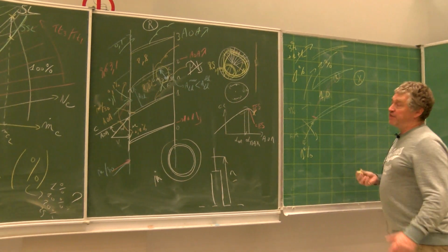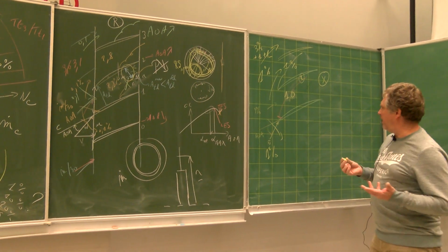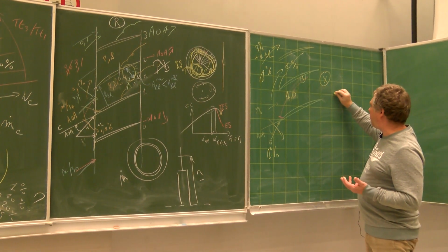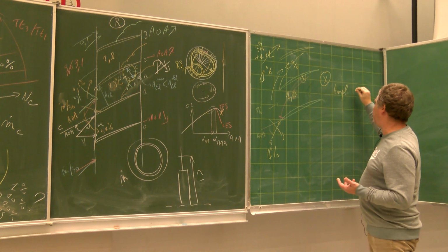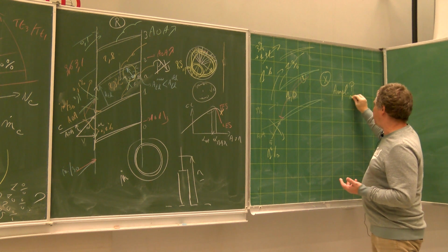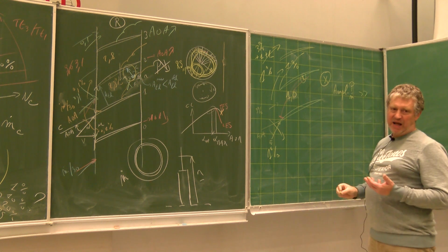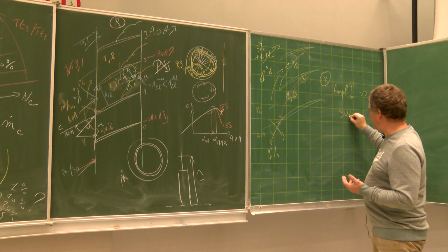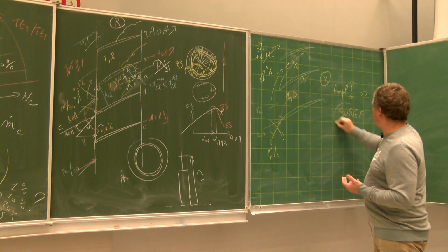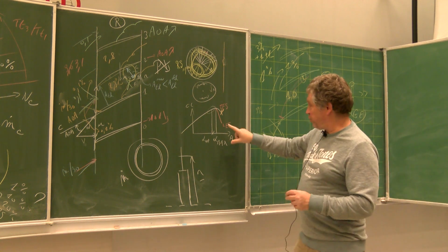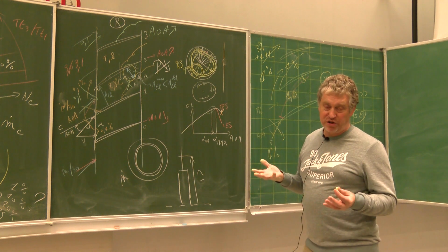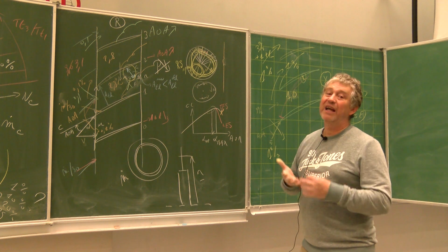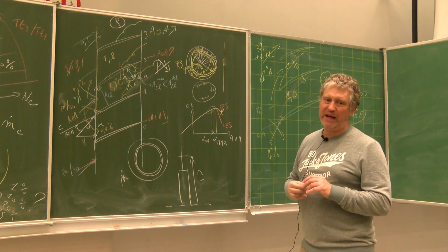phenomenon. And that's why we give to this phenomenon that is of a much larger amplitude, the amplitude here from a pressure and mass flow rate point of view is much larger, we give another name. It's also a stall, because you see it's coming from a separation that we call a stall, but this is originally a leading edge stall instead of a trailing edge stall.